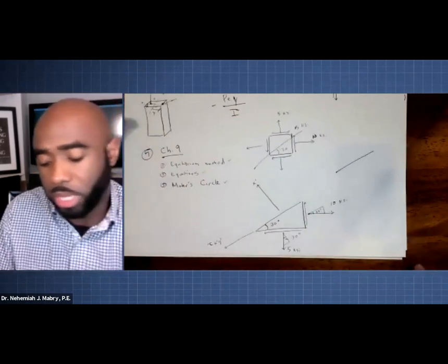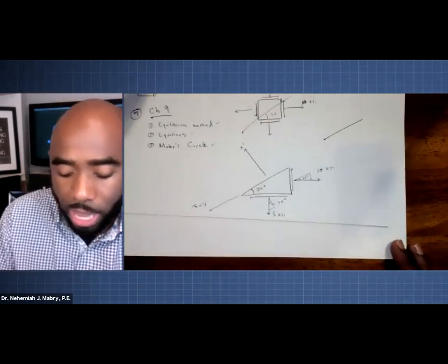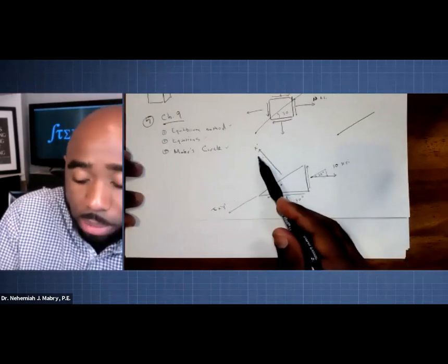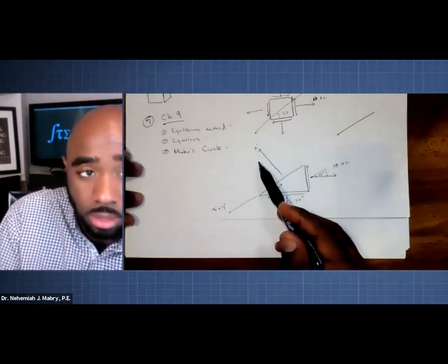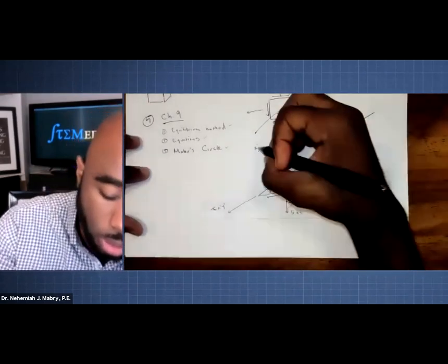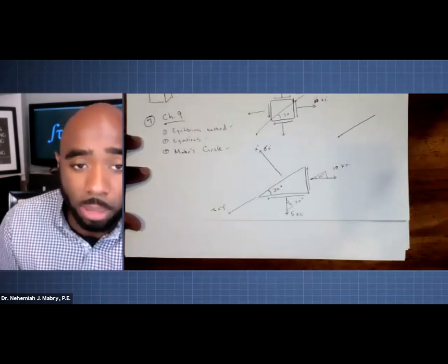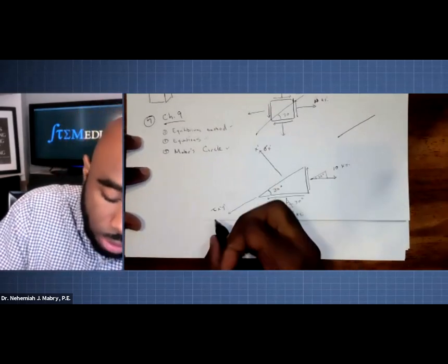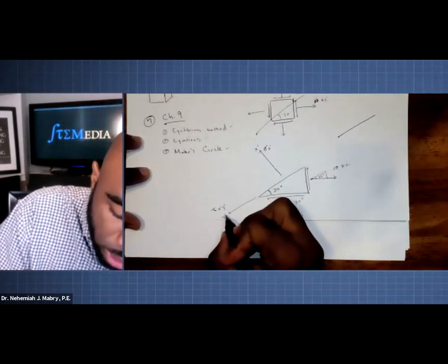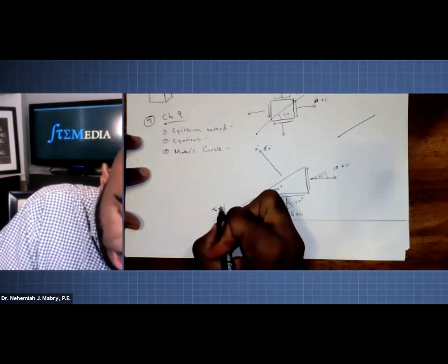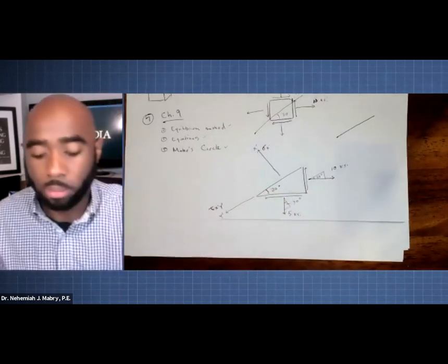And what you're going to be doing in the equilibrium method is remembering how to gather all of the components in the x prime direction, add them up to solve for what this is ultimately going to give you, sigma x prime, and then all the stress components in this y prime direction, you're going to sum up and then solve for tau x prime y prime.